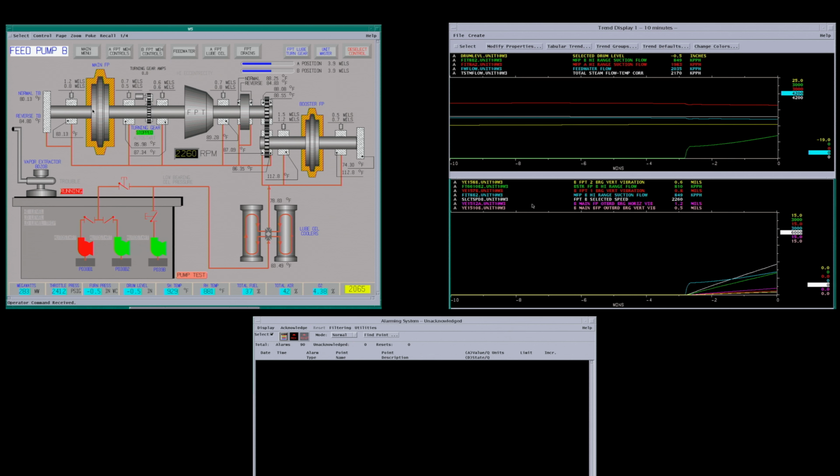Ways to prevent cavitation: you can keep higher suction pressure, limit the throttle pressure. There's some changes to the impellers that can be made. Usually cavitation is pretty detrimental to pumps. And you also have to have minimum flow on these things, otherwise they'll produce a lot of heat and do damage. That's why we have the recirc valves.